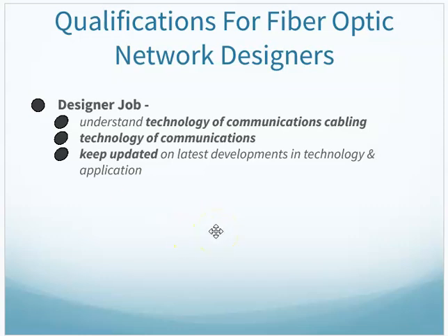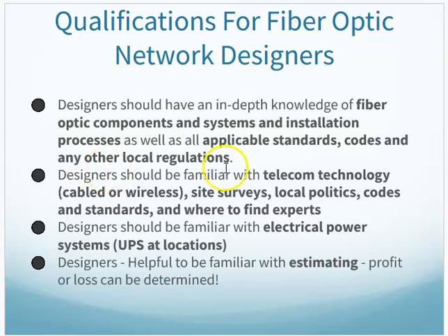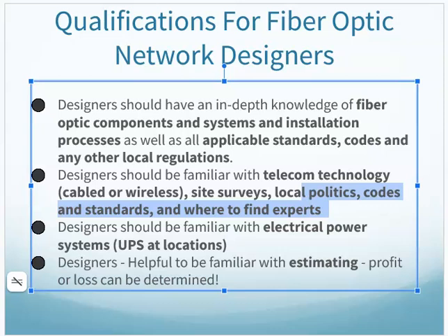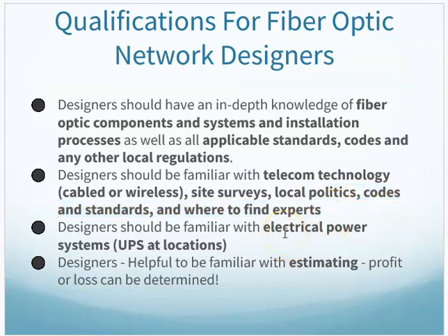Your fiber optic network designer really needs to understand all the cabling and equipment that you're using, the technology of communications, how these things are functioning, and keeping up to date with practices or even changes in laws and regulations that come along that might affect how things are done. Designers need in-depth knowledge of the cabling, the equipment and so forth, standards, codes. They should be familiar with telecom equipment, site surveys, local codes, and standards that might be in an area that you have to adhere to.